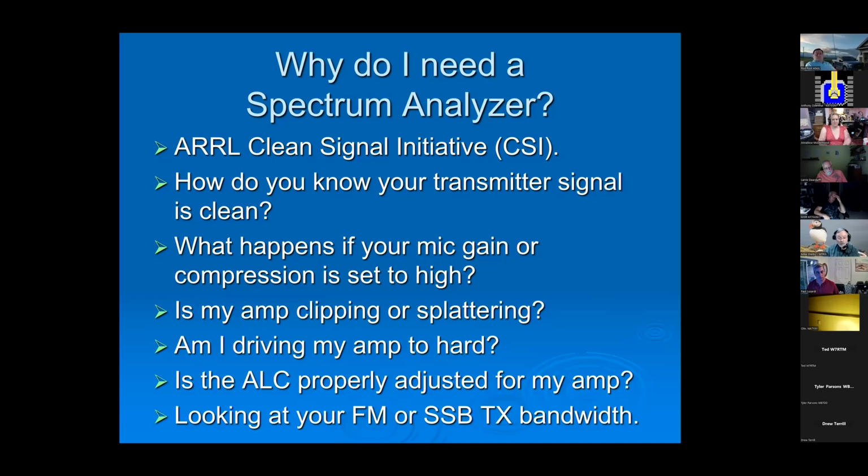You need to know what the IMD value is of every single band, because there are different band filters that get loaded in when you flip between bands. And you want to know the IMD at the top of the band, and at the bottom of the band, and at the end of the band. So those are the kind of statistics and numbers that we need to know in order to make a quality selection of our ham equipment.